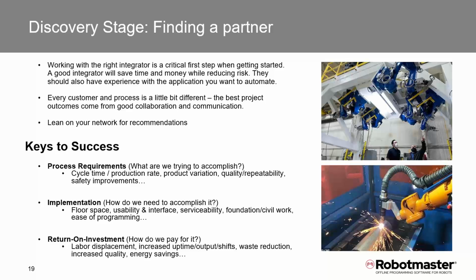The very first thing is cycle times and production rates. These are some questions they're going to ask you. What are you expecting? Do you have a production amount that you expect on a monthly or weekly basis? Do you have a cycle time that you're aiming for? How quickly do you want to produce each part? What are your production runs typically? Are they one-offs, or low volume in batches of 5, 20, or hundreds? Are there any implementation limitations like floor space? Can it be serviceable? Is the programming easy? Does it have to be easy?